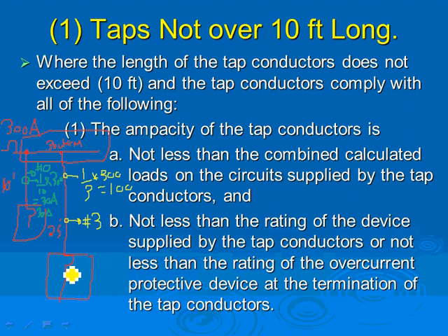And then number 3, how much current can number 3 give me under the 75 column? 100. So then what do you need to put here? 100 amp. So the smallest conductor is going to be number 3. It's landing on 100 amp to limit the current that you're pulling to 100 amp, otherwise you exceed that conductor. You have to put these in a conduit to protect the conductors. You have to land this conductor in an overcurrent protection device. Use your circuit breaker to limit it to 100.